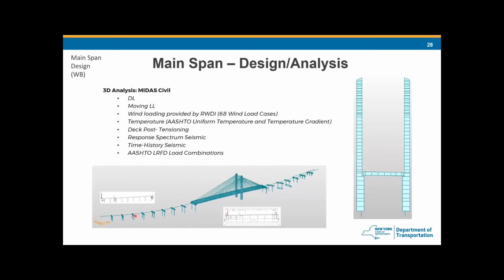And you can see this view of the model, and the cap beam, the columns, and the floor beam and edge girders, and the spine of the approach is modeled with linear elastic beams, and the cables are modeled with truss members, and the foundations are simulated by a 6x6 matrix.